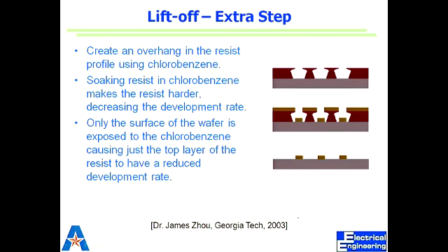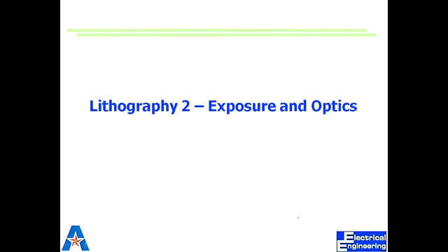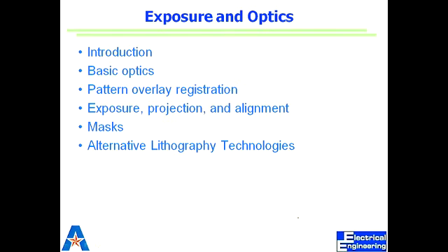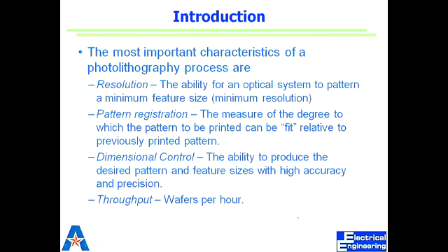We will be revisiting resist properties and all those over and over, but let's now focus on the optics side of lithography. Because we have this appreciation now that lithography is not just optics or just resist, they all come together. As a designer or as a process engineer, I have to know all those things: the energy that I use, what kind of resist I need, what the issues with thickness are, how I apply resist, how I do development, but also what kind of light I use, how I register those patterns, and what it takes to get my light right to do that.